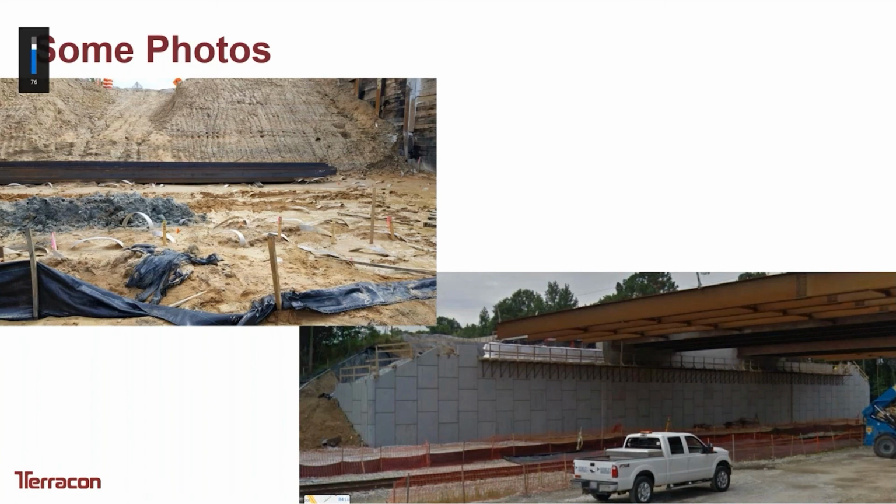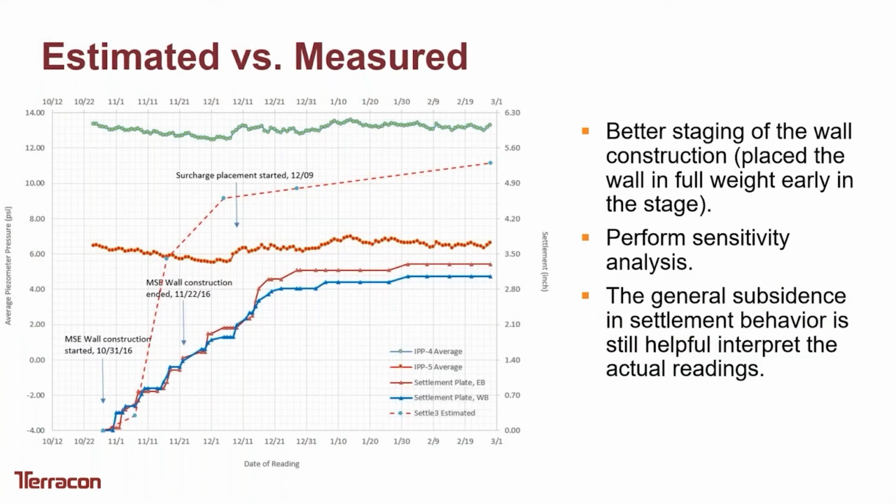Expected amount of settlement for this project? So it depends on the project. What we were looking for is the Virginia Department of Transportation requirement. What they say is that once you have your fill constructed for the bridge approaches, you need to have no more than 1 inch of post-construction settlement within 20 years. So it's very specific. Beyond the 100 feet of the approach, our post-construction settlements were set as 2 inches.